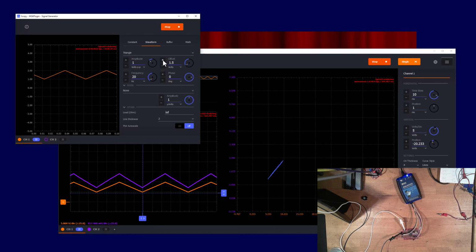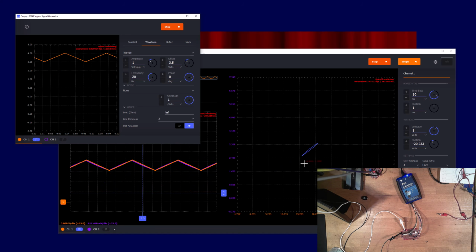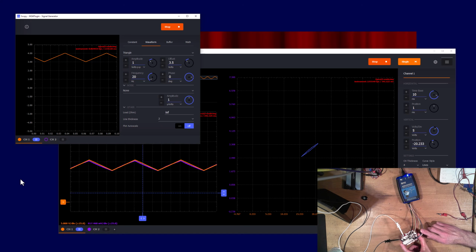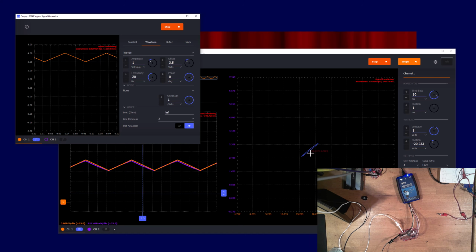So up 1.5 volts, 2.5 volts, 3 volts. Okay, and notice the slope is flattening out, so my resistance is increasing. And notice that, I don't know if you can see this or not, but the light is flickering just a little bit, but we can see the filament up here. So yeah, this is where it's at. So as I increase the average, as I increase the continuous dissipation in the bulb, my resistance increases, conductance, or the slope of this line, is lower.